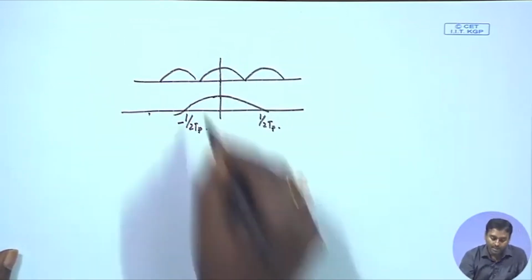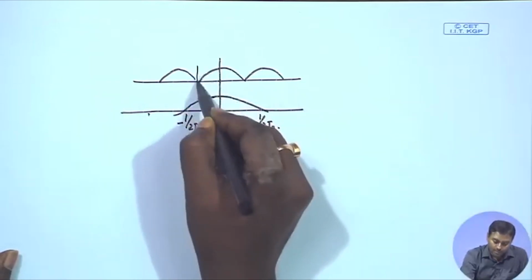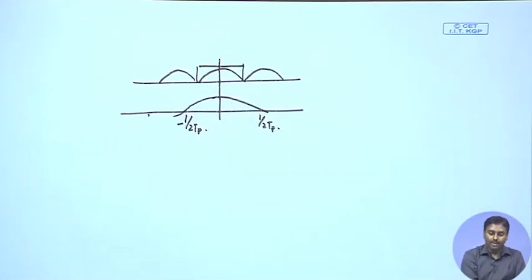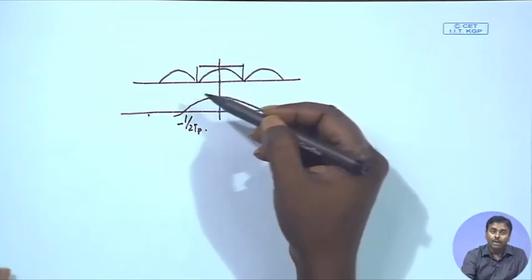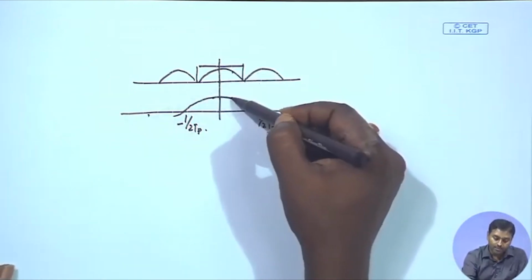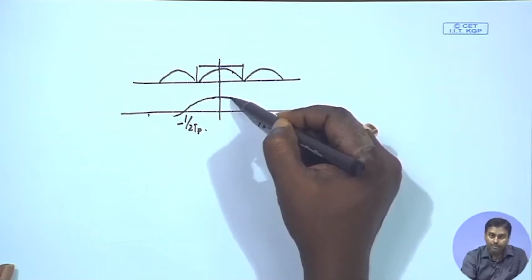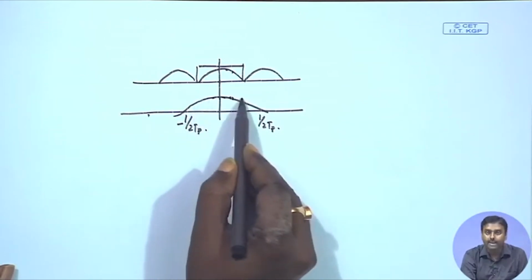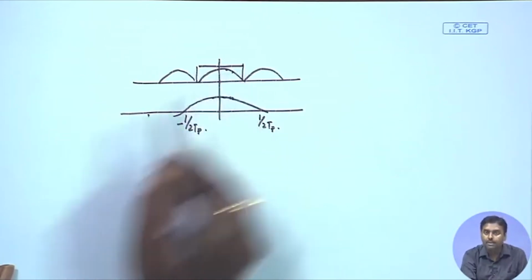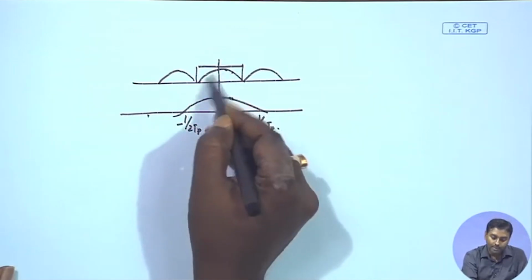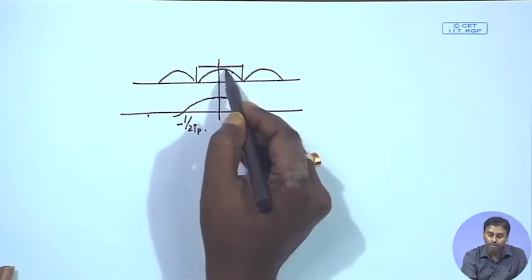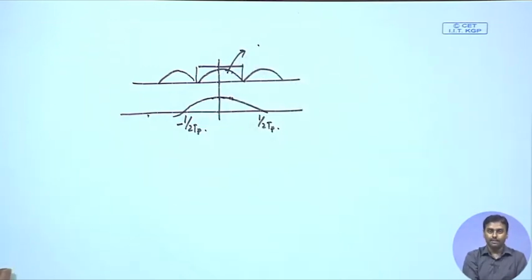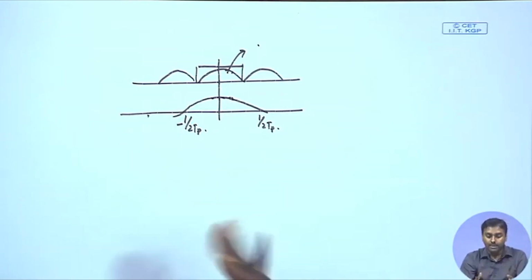If you see what is happening, earlier what we were doing, we were just putting a band pass filter, getting our signal back, but now my signal is a composite signal, a multiplication of these two, and unfortunately for me, this is getting multiplied by this, which does not have a flat characteristic over the entire frequency band of interest. So, because of this multiplication, there will be a distortion to this signal. So, whenever we put a pulse like that, there is a possibility of distortion.